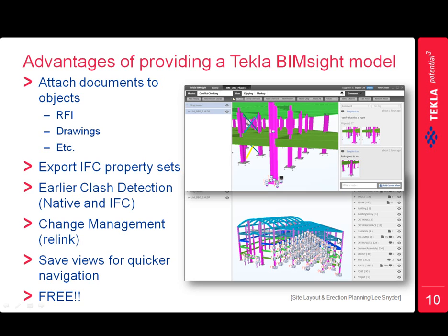If you just had this phase 1 modeled in, and then the detailer sent you the other phases and so forth, you don't want to lose any of these documents or things that you have linked to those pieces. So we have a relink function where you just reload the IFC file and it'll link everything to those individual objects, so that you can continue to build off what you've already done, but still have the latest and greatest version of the model.